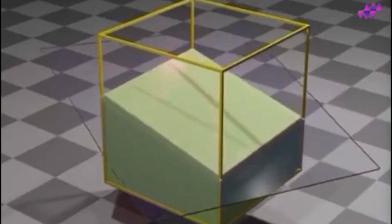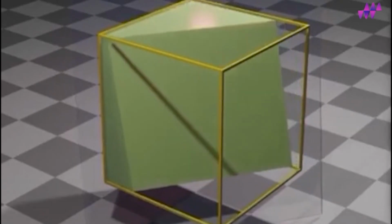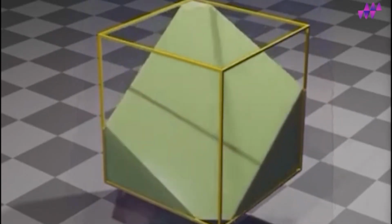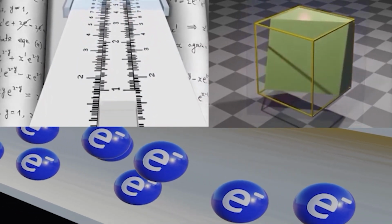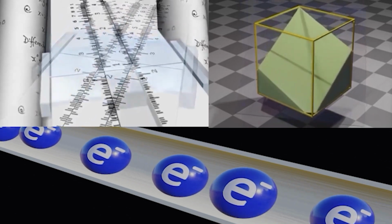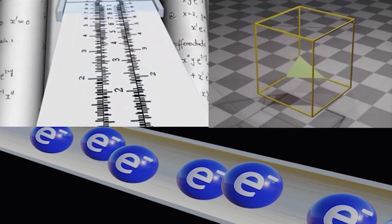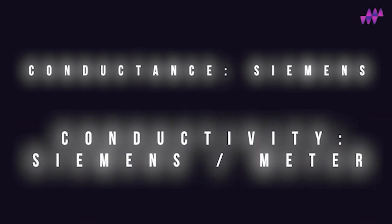When the length of a material is reduced, the material conductance increases, and when the cross-sectional area of that material is increased, the material conductance increases, and vice versa. Material conductance is measured in Siemens, while material's conductivity is measured in Siemens per meter. That was the first element.